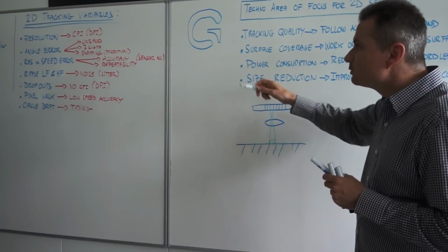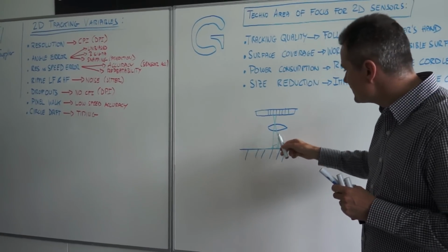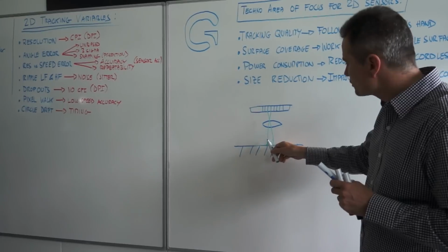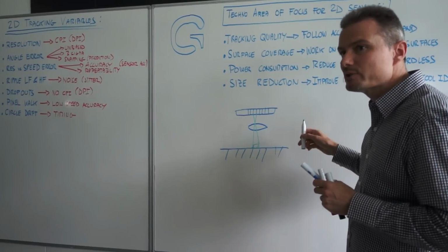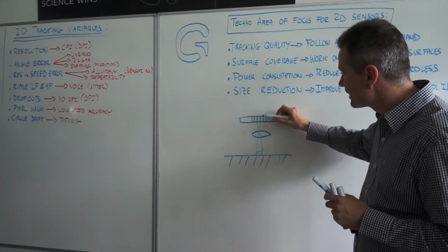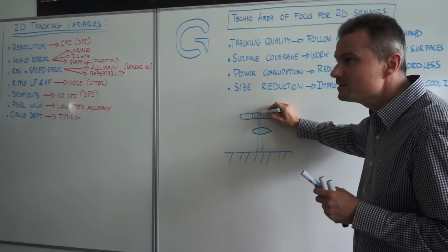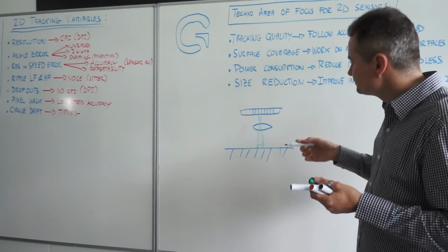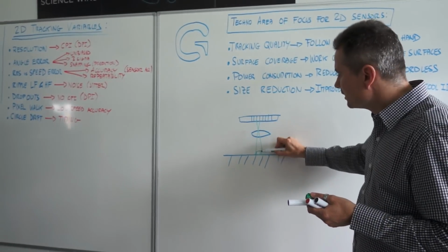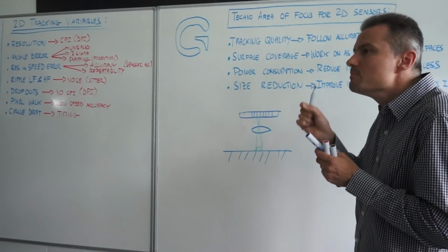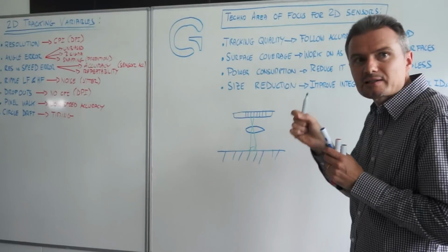And what we say when we say count per inch is how many of those pixels we can put in 1 inch. This is the resolution of the system. And this is the optical resolution of the system, because the system has a size here that is fixed. It has an optical lens that gives a given magnification. It's the optical formula, and it builds a pixel size on the table. And this is the minimum item the system can see natively.